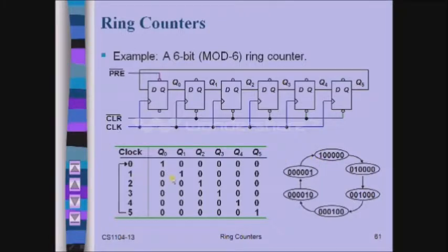During the first clock pulse, the data would be shifted out, as all the flip-flops would be shifting the data they are holding towards the outside. That means now Q0 will be shifted towards Q1, and Q1 towards Q2, Q2 to Q3, Q3 to Q4, and Q4 to Q5, and Q5 would be copied or loaded into the first D input.